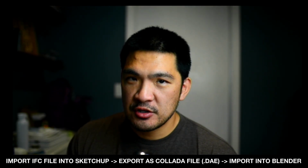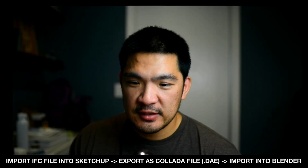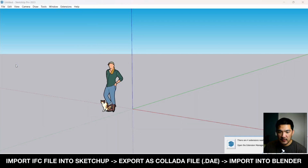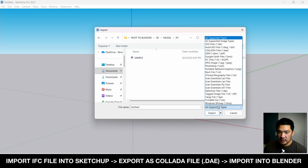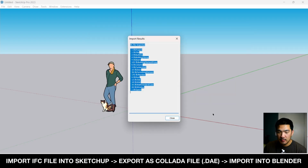But there is another workflow that I've used for years before I knew about the Bonsai add-on, and if you're coming from SketchUp, this method may actually be more useful to you. You can actually import IFC files into SketchUp. Go to Import and find your IFC file, and you can see that under supported types, IFC is included. Once it's imported, you'll see the same geometry now in SketchUp.